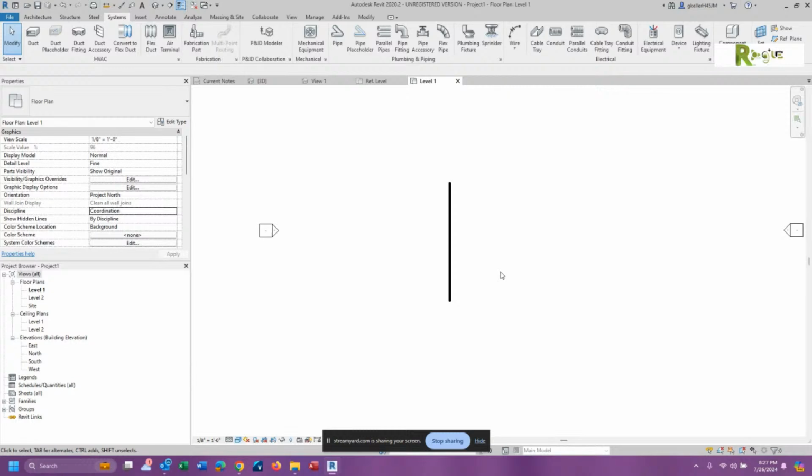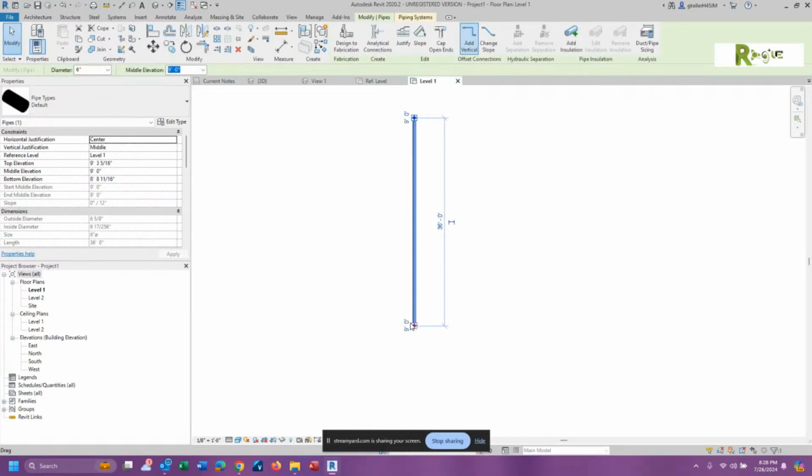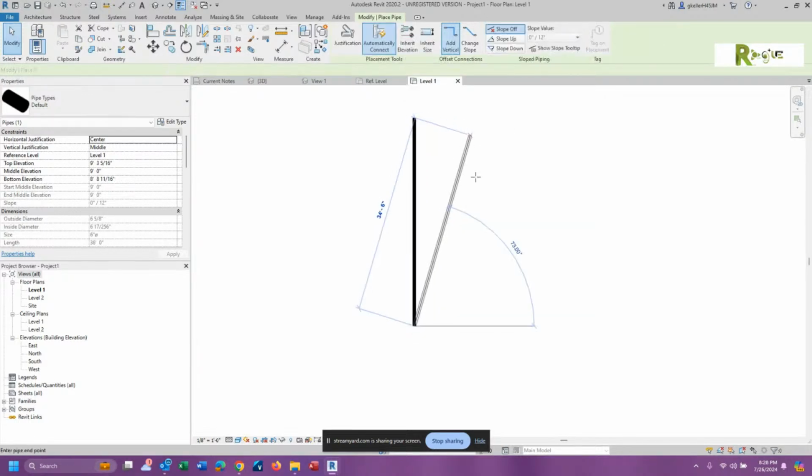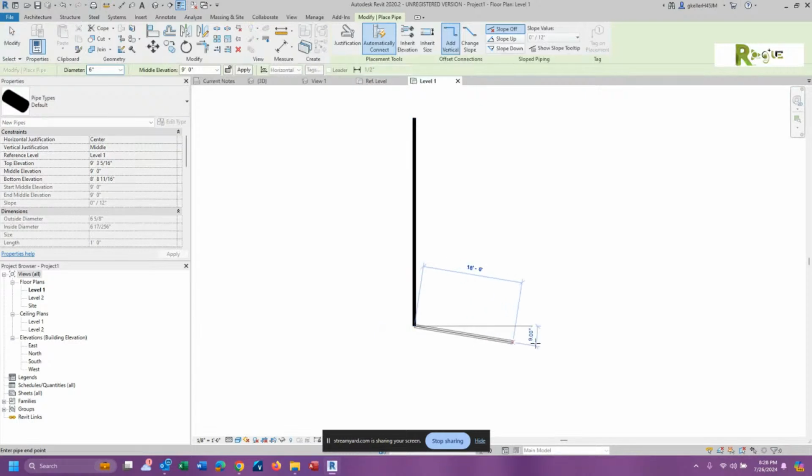Oh, that's beautiful. Black. Because that was this type of pipe that it was. Okay. Now, normally, if we had a piece of pipe and we wanted to extend it to draw some more, we could pick that pipe, and right click right over top of that little dot and say draw pipe. See all those things right there? See, that's a very important click to do. And click.